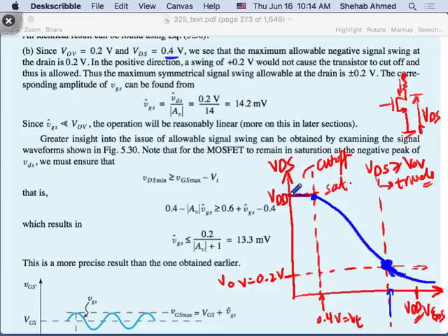Here it's VDD, here it's my overdrive voltage, and then the corresponding VGSB from the equation that we have from a few pages ago. I defined this point. I can draw this curve if needed, but I will not be operating here anyway. You can draw the extension here.